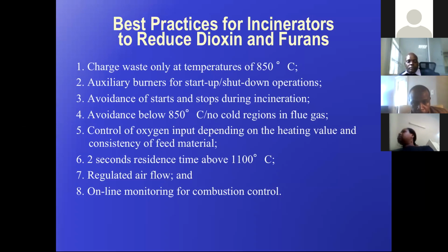Now my understanding with the viral load waste is that it probably consists mainly of plastic and some liquid waste, and that plastic can serve as a heat source as well, so it burns well and allows you to get temperatures up there. So when the temperatures are elevated to the right point, those auxiliary burners or whatever other auxiliary heat sources you might have can be shut down once your waste starts burning, right? So if you have a high plastic waste, there's no reason to have that.